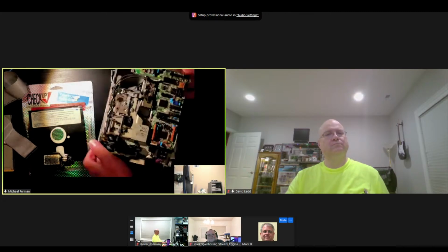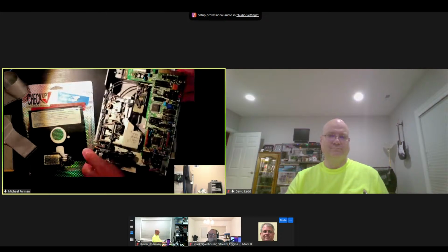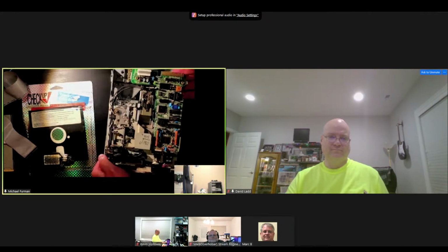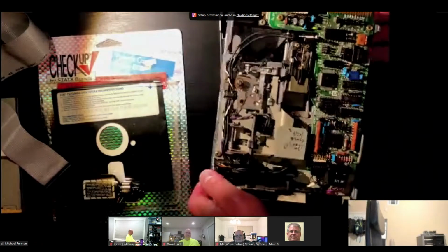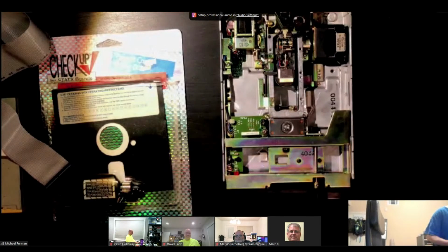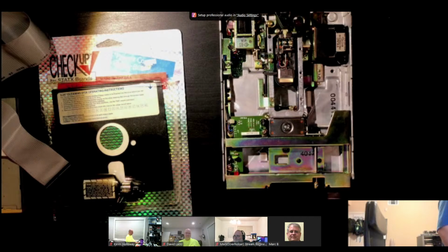And so if you want to use this 1.2 drive to read a 40 track double density disk, what you have to tell this drive to do in whatever software you're using for imaging is to step the head twice every time, because you're going to have tracks 0 to 79, but the ones in between don't have any data on them. So that's what you have to do. And many people do not know that or think about it.